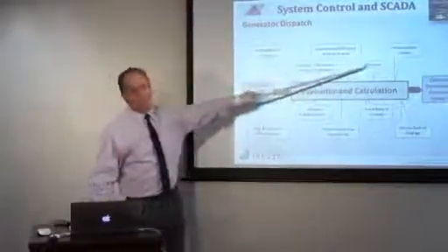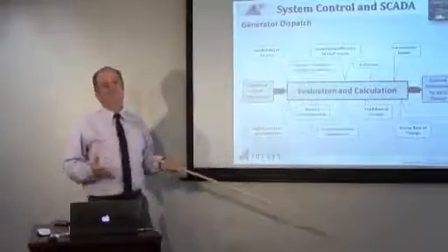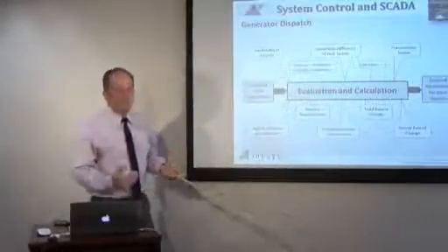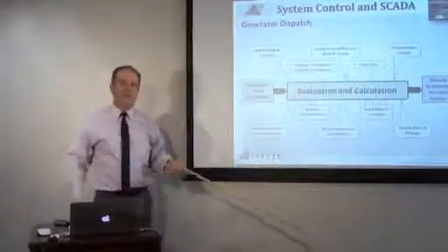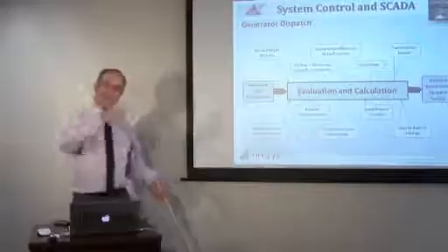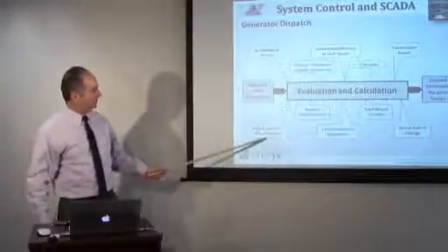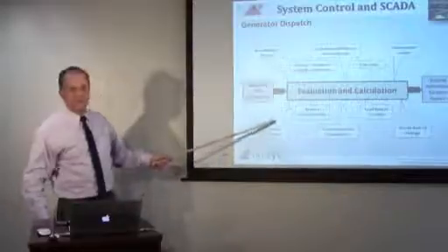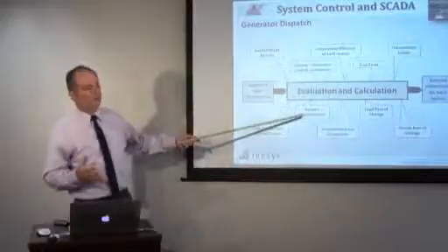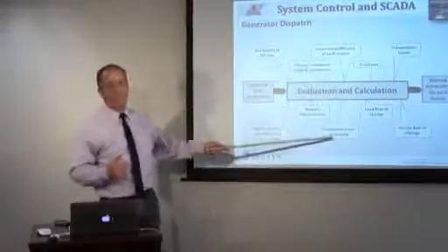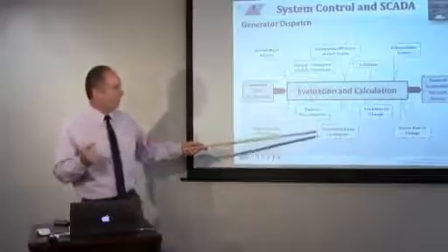The fuel costs. What's the cheapest fuel cost? What do we have ample supply of? Transmission line losses. If I start this generator instead of this one, I have to pay for the transmission line losses, the I-squared-R losses. How about high and low limits on each source? Are we getting too close to its maximum? What about reserve and spinning reserve requirements and transmission line constraints? Boy, if I start that one up, I don't have any room for my scheduled power.